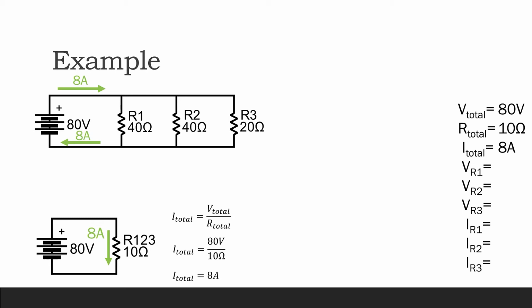So let's think about the voltage here for a minute. We can choose any point on our circuit and arbitrarily call that 0 volts, and then every other point can have a voltage relative to 0. Oftentimes the negative side of the power supply is chosen to be 0 volts. So let's call that 0 volts right now. We'll make a little mark on our page to remind ourselves. That point is 0 volts.